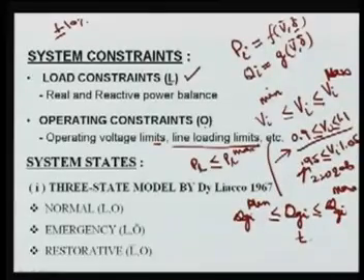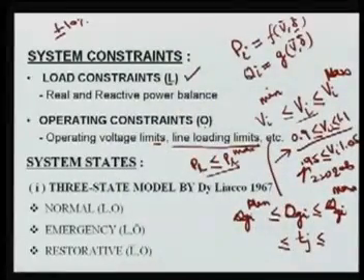We can also go for the tappings at any bus. Let's suppose a transformer is there, so it should be within its transformer tap limits. So these are the various limits, related to the voltage, line flow or branch flow, reactive power generation, and the transformer tappings, which basically come into the operating constraints of the power system.